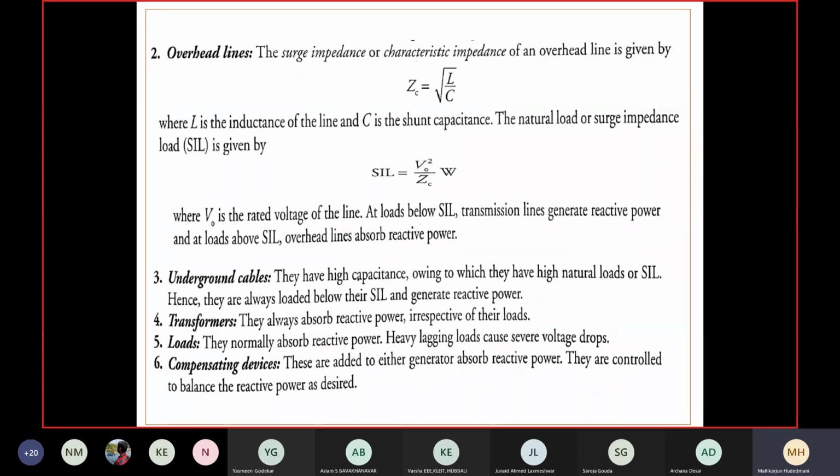These compensating devices are surely working with intelligent computation algorithms or mechanisms, taking care of what the power factor is right now, what the terminal voltage is, and accordingly they keep compensating the required correction, either incrementing the tap of a transformer, adding a capacitor, or changing the load or controlling both, however it is planned.